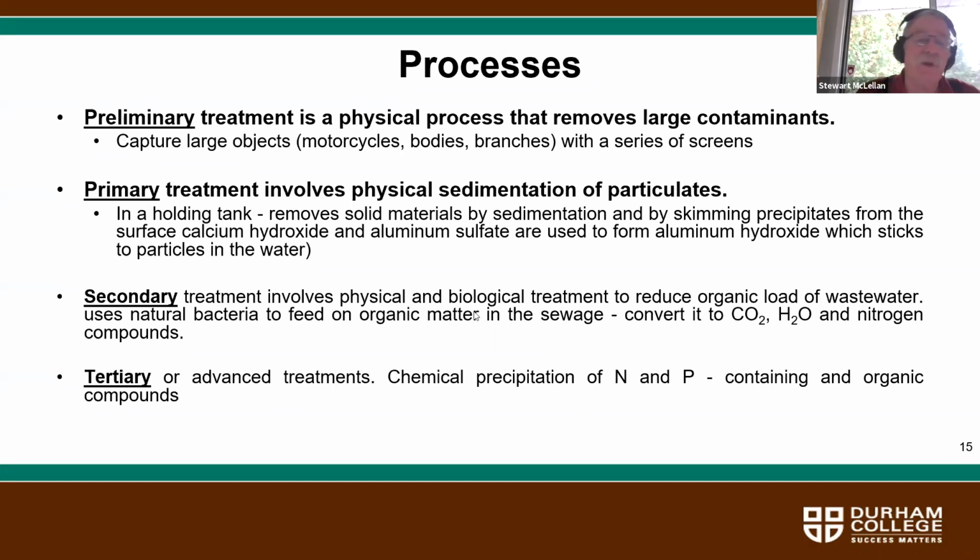Yeah, so municipal treatment plants are hard pressed to remove the biological oxygen demand from normal sewage without also receiving wastewater from industrial facilities that is very high in BOD, which would also require removal at the wastewater treatment plant. So that's why municipalities regulate BOD in effluent discharge.